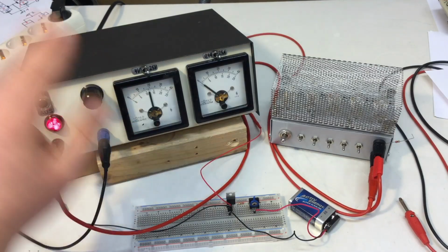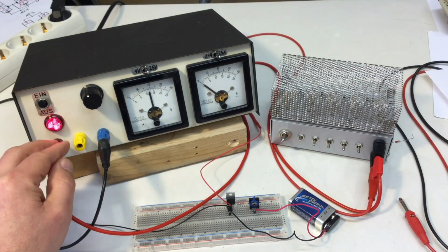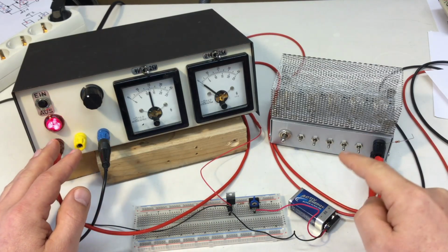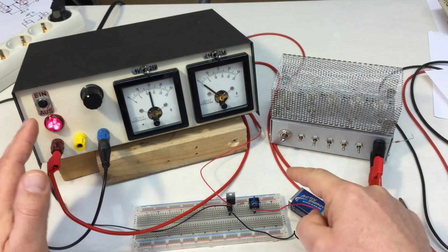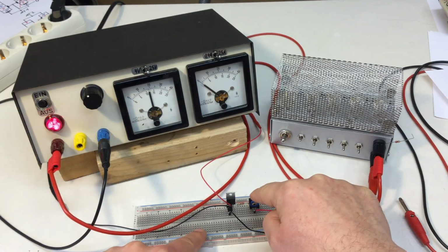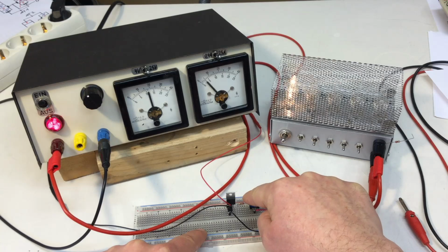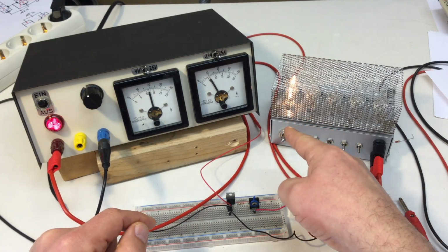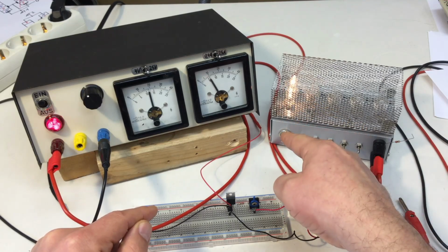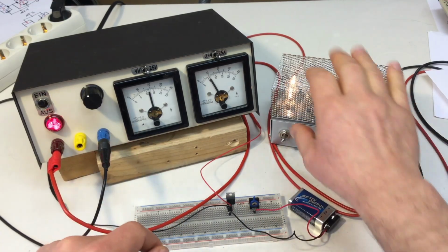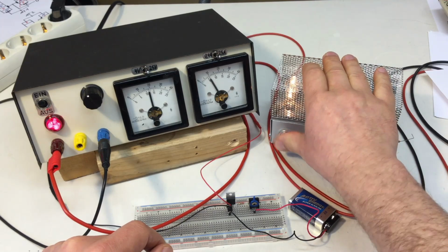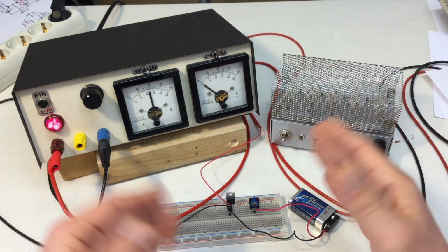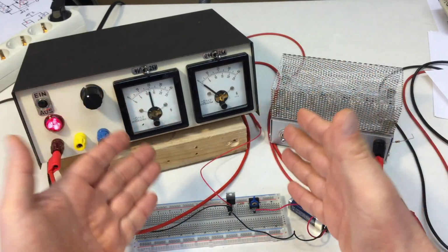So at the moment, my positive output of the power supply is connected to main terminal 2 and the positive of the battery is connected to main terminal 2. And if I take my momentary switch and give a short pulse to the gate, positive pulse, the TRIAC switches on. And it stays on until I break the circuit. Wonderful. But you can do more with the TRIAC.